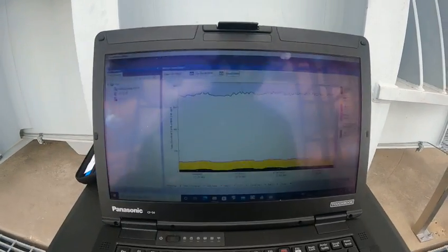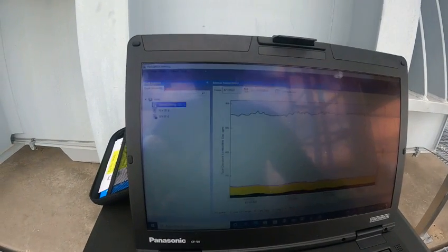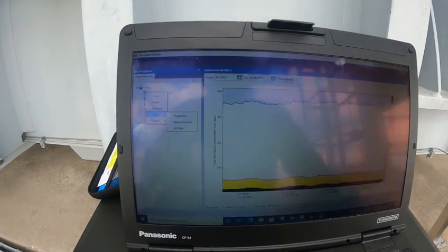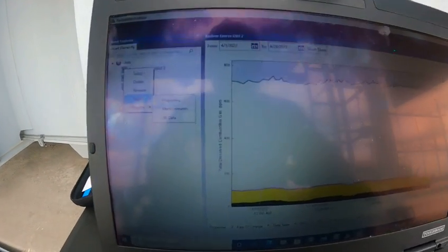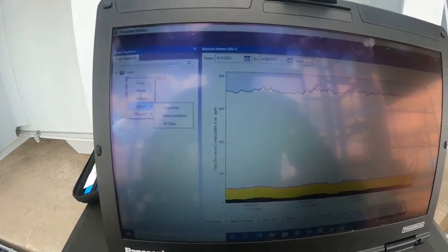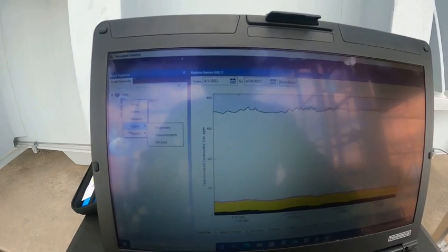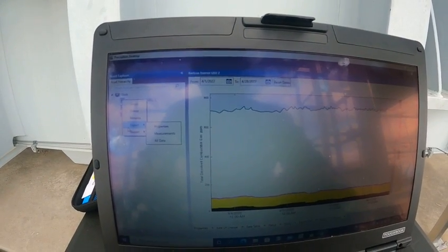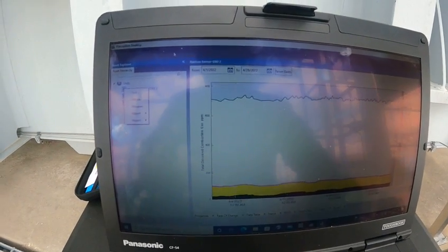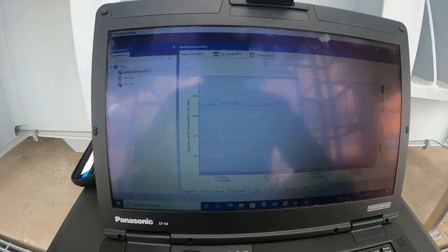Okay, sorry about that. So now when you right click on that icon, it gives you an option to export. So what you do is you go ahead and export properties, measurements, or all data, and then you can get that. And if, let's say, anybody wants to review the data, and we have an event, you show a little bit more hydrogen, or hopefully no acetylene, then if they ask for a report from this, then you can get it from there. It's a very good tool to use. Like I said, trending the charts, it gives you all the options.